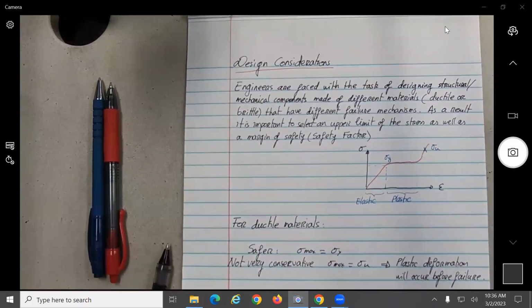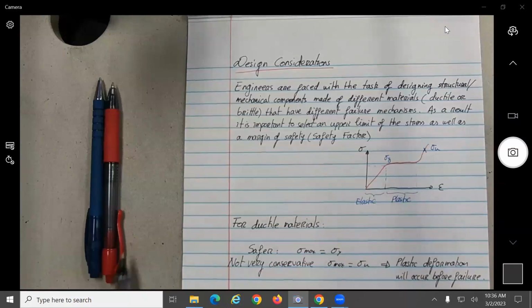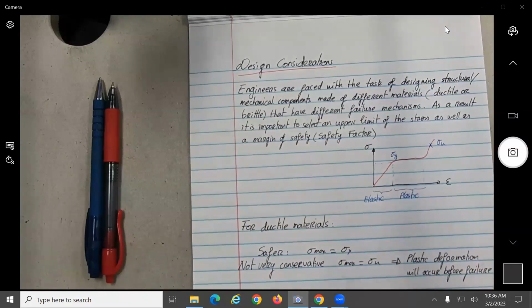Okay, but when can that be important? Let's say it's a component of a machine that is easily replaceable, and it happens that the weight is critical, no? So if you want to save weight, maybe you can make the structure smaller, but instead of taking the yield, you take the ultimate, no? Okay, and say, okay, you know what? That piece of the structure is not that critical. Let's just save some weight, and instead of using the yield, we can use the ultimate. It depends on your criteria. The whole thing depends on your design criteria. Okay, now let's look at, so this one is a lot easier.